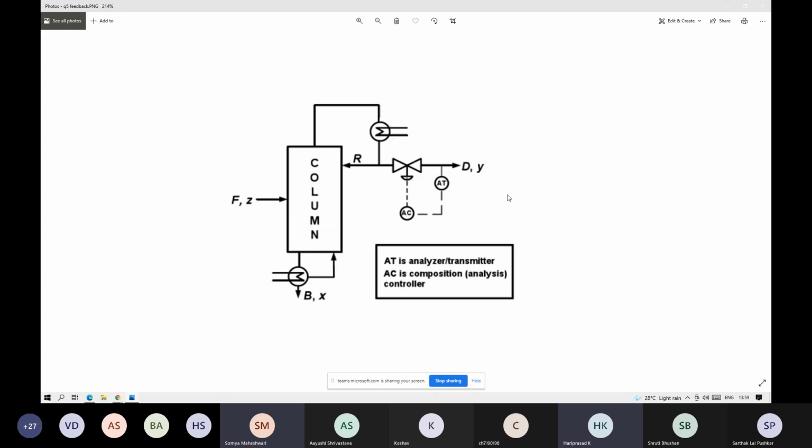Yes. So even if you place here or place here, so let's say you are trying to say that instead of controlling the distillate flow, I will go and change the steam flow to increase the heating. That's your argument, right? Yeah, kind of, sir. As in the example that we covered in the class, in the feedback model itself, we measure the X at the output, then we change the X2, so that we'll get the required X.